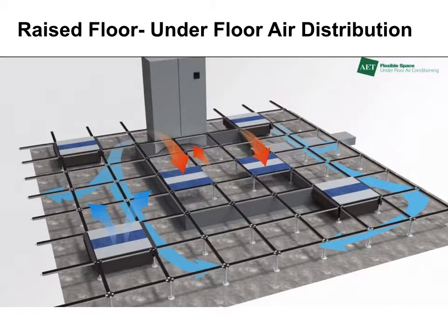And again, as a reminder, we talked about raised floor underfloor air distribution, also known as displacement ventilation. And if you recall from our previous lectures, we talked about how air can be provided at the plenum space, use fewer fans, and yet be able to have little controls in the floor so that you can control the amount of air that you're exposed to.